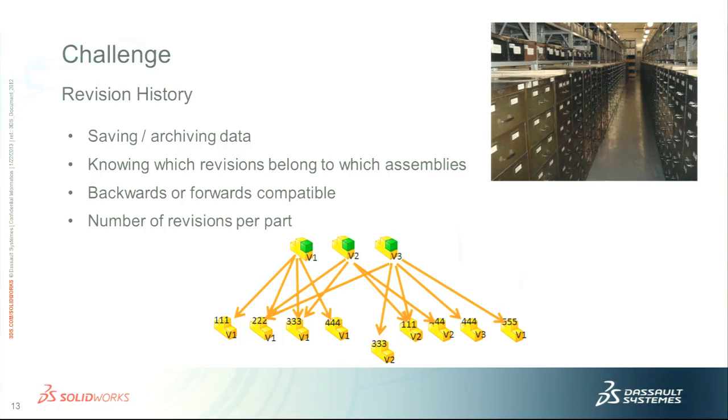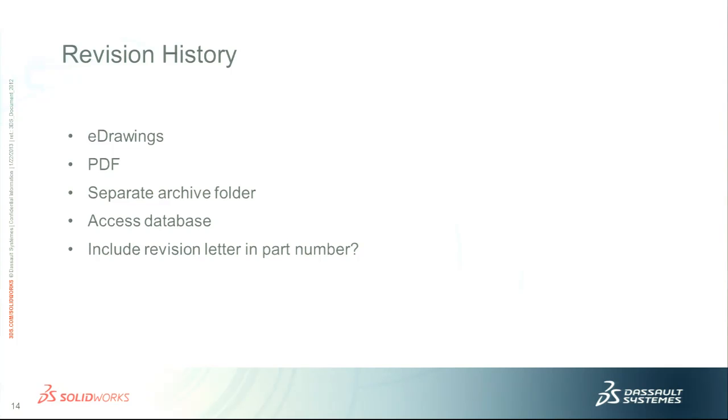All right. So the way we handled it is we created e-drawings. Our SolidWorks drawing file was the one we worked on, so if we ever needed to make changes, but the e-drawing was the master. So if we needed to order a part for sending out to our vendor, we sent them an e-drawing only. We would not send them a SolidWorks drawing unless it was a sheet metal person who wanted the DXF so he could cut the parts out.